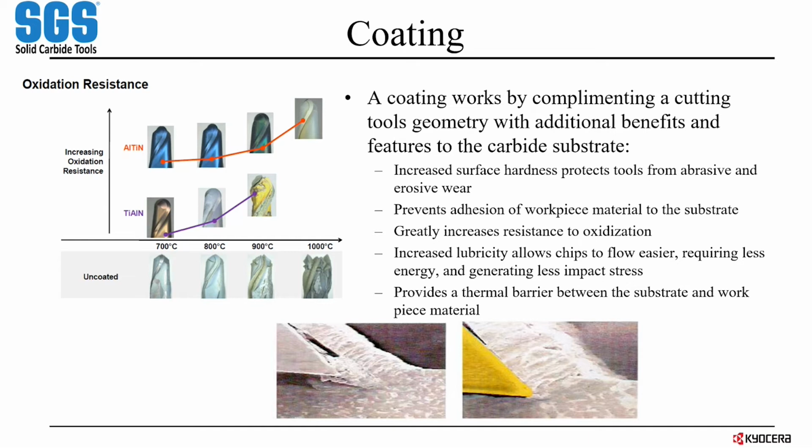There's a ton of heat that's generated in that cut, and your coating is really going to help fend that off. It's going to spread that heat out across the coating instead of allowing it to centralize in that cutting edge. Because high temp alloys, the whole purpose of them is that they can handle high temperatures. They have low thermal conductivity, so that heat really stays centralized right there at that cutting edge.